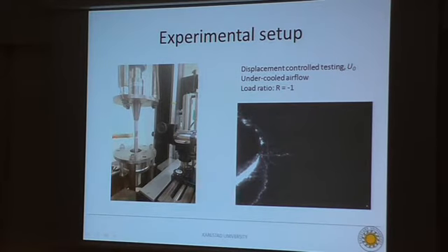What we are doing during the experiment is that we are trying to get the crack initiation from the beginning by increasing the load in steps until we get the crack initiation, and we will try to stop it after approximately 0.5 millimeter, and then change the load and keep the experiment running in intervals of 0.5 millimeter, where we will change the load after each step.